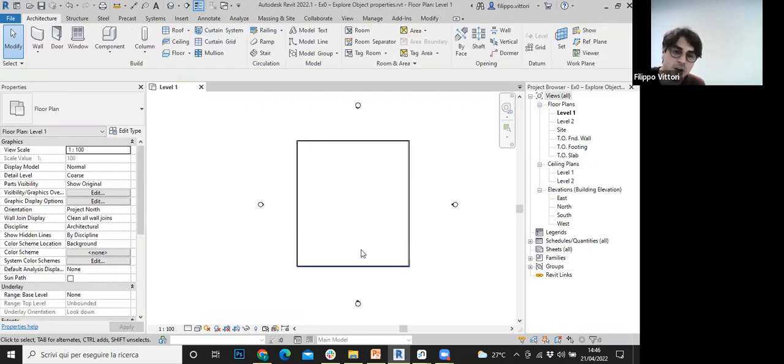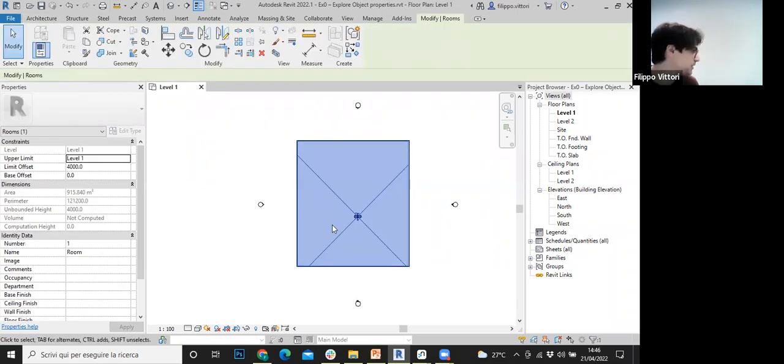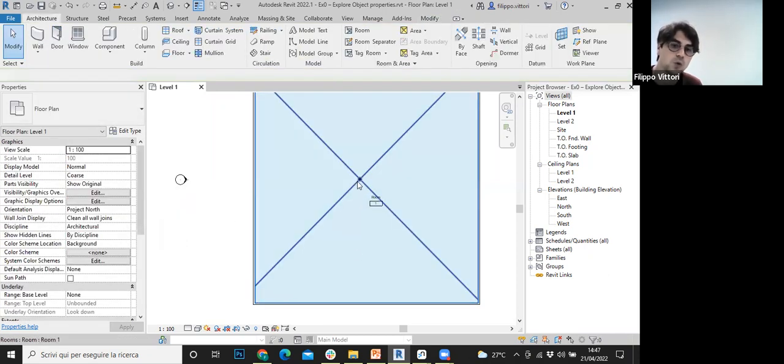Okay, so here we inserted some instances within the Revit file, the Revit database. We are writing something somewhere in a database that is not showing now, but we will see later. In addition to this, we can also insert within the project instances that are not physically existing. This is the case of a room, for instance. A room is not something that exists within the environment. But if you consider the room an object, you can insert it within the project, and so you can use all the information to insert logical entities within your project.